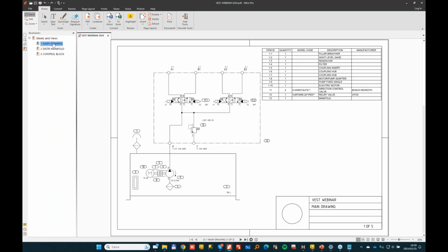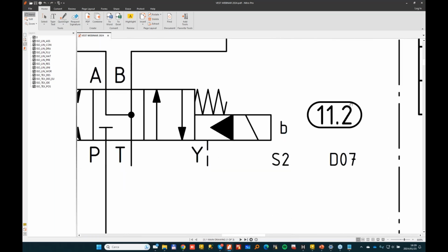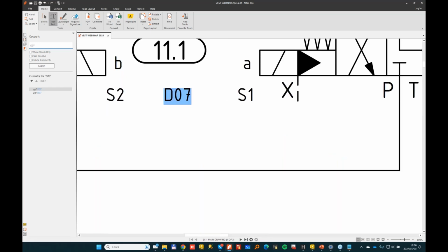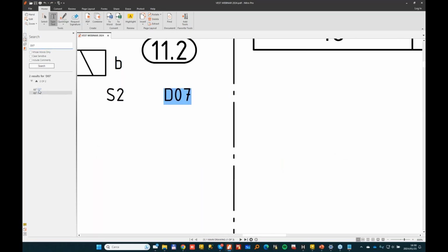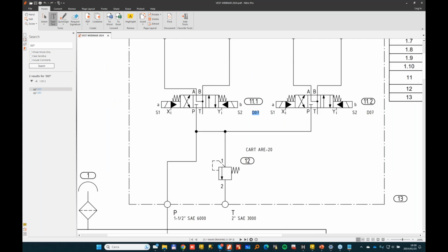Remember that the PDF generated directly from the AutoCAD engine has all the layers, has very high quality because it's all vector entities, so all the text can be edited if you have editors, but can also be found just by using the search inside the PDF.